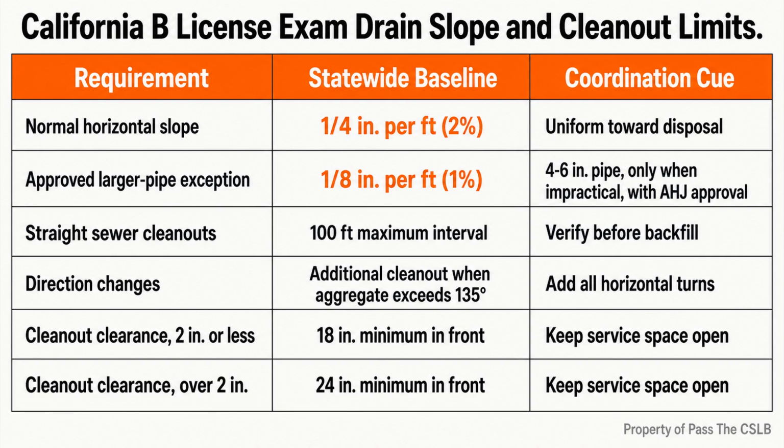This is one of those details that is easiest to protect early and hardest to repair late. Before walls, cabinets, mechanical equipment, paving, or landscaping lock the space down, I look from the cleanout outward and ask whether a plumber can actually work in front of it. I do not count open space that is shown on a plan, but will be occupied in the finished building.